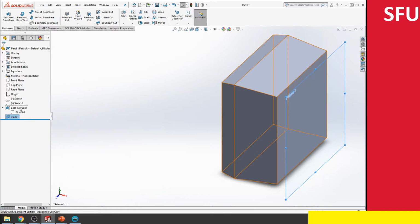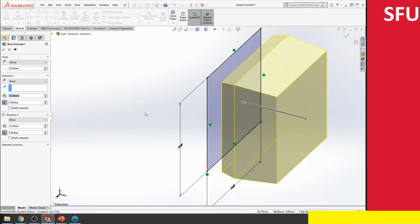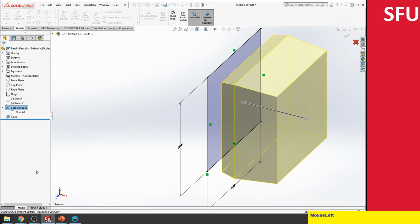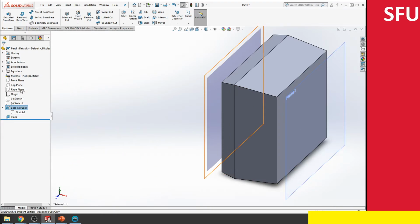So the first one is if I now try to end this feature, you'll notice that my plane has gone missing. The reason this has happened is because of the way the SolidWorks creation is structured. What SolidWorks does is you're actually building your elements on top of each other. So it thinks that the plane has been built on top of the extruded part, and so once you try to edit the part, this isn't actually available.